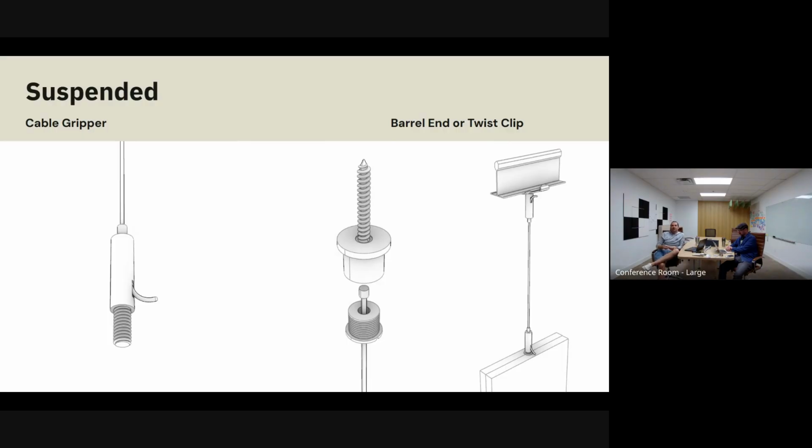That one's what we call a Mel grip locker. I just pulled it out of this baffle, right? So 90% of our baffles are going to have right here a 1/4-20 nutsert, which allows this hardware to just screw right in. Super simple. The other 10% of our baffles have a stud that comes out of it, and so we use a female grip locker, same exact application. It just screws onto there instead.